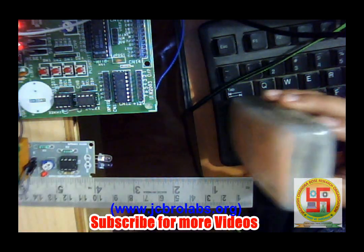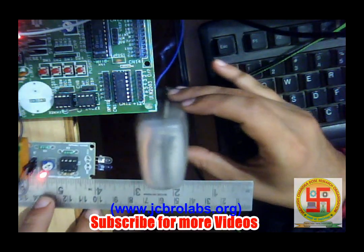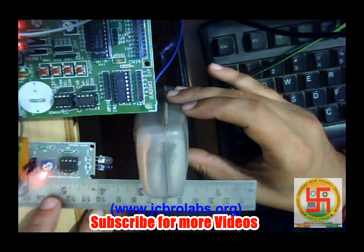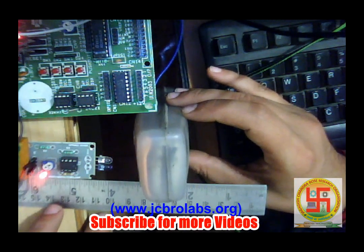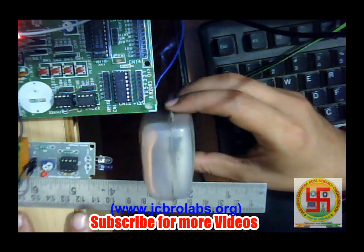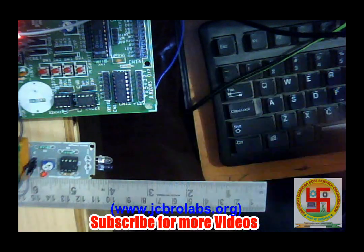Now it will not detect at 4 centimeter, and let's see up to where. Okay, now it's detecting it. Now its range is nearly 1 centimeter only. So when the object is at 1 centimeter distance, only then it is detecting it. So this is how we can change even the distance or the detecting range of the IR sensor.